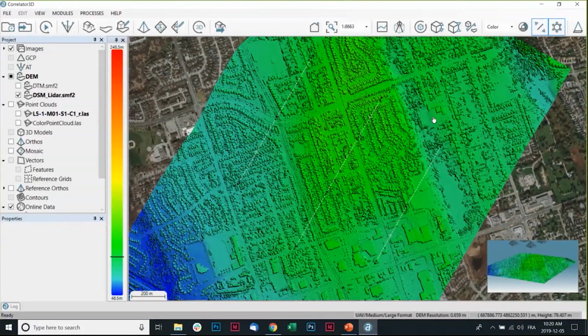Once it's there, we interpolate all the points that belong to the cells. So if there's more than one point that fits in one raster cell, we'll try to interpolate them in order to have a surface model that will be used for your photogrammetric processing.